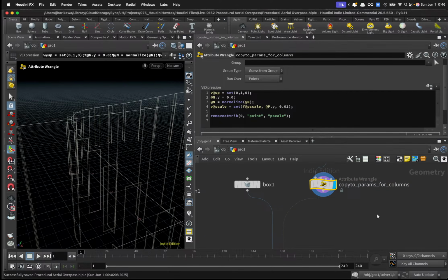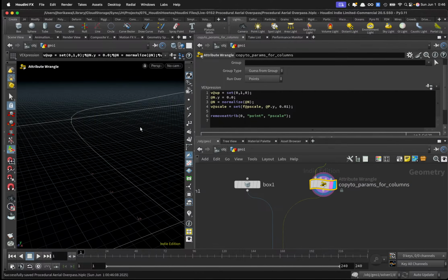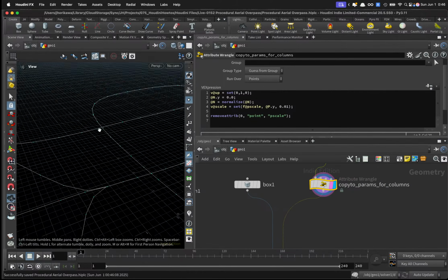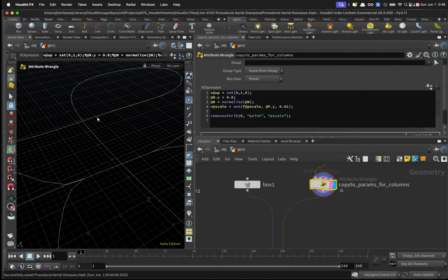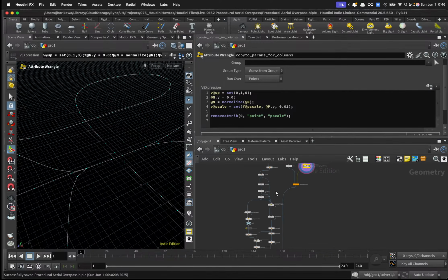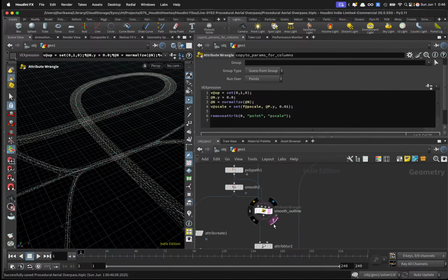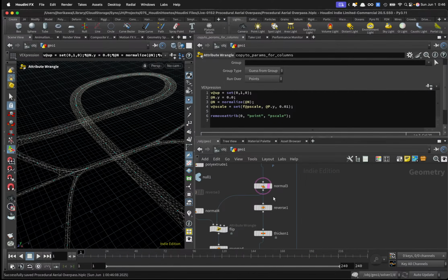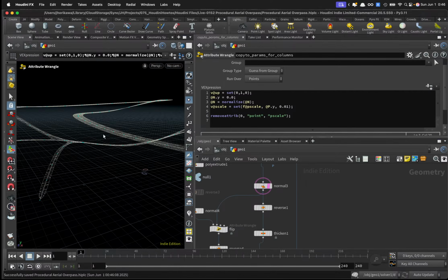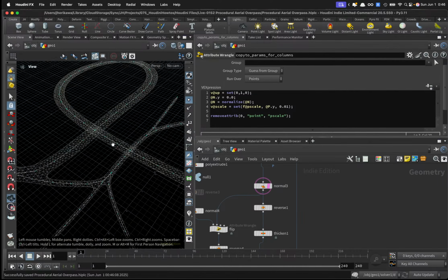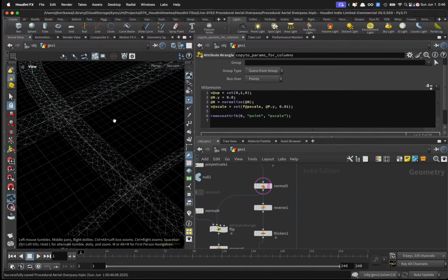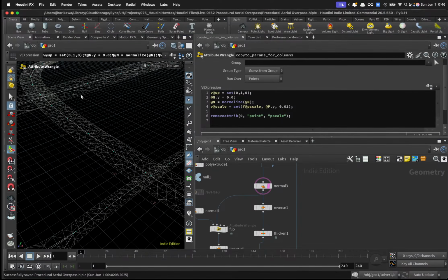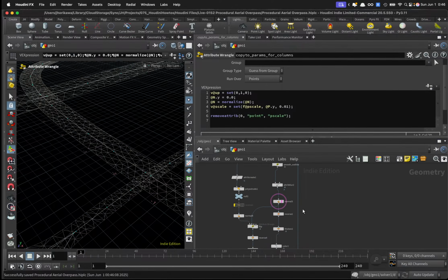Now, the thing you need to check is whether you have a face underneath from that point where you want to place the column. And the face is created somewhere around here, right? So using this as a guide, check the intersections going underneath. And if there are intersections when creating an array from those points underneath, then just skip creating that column.